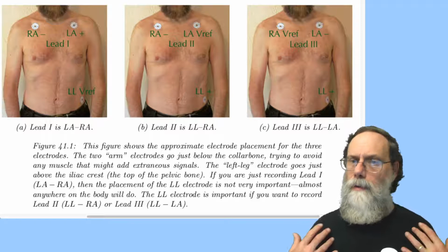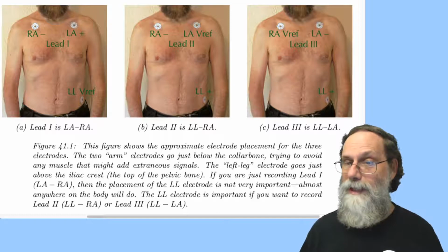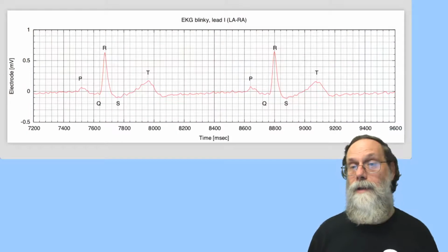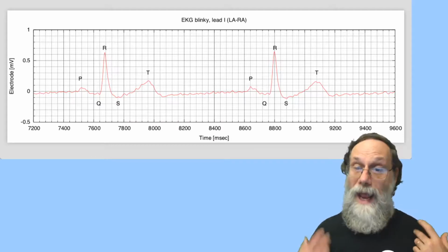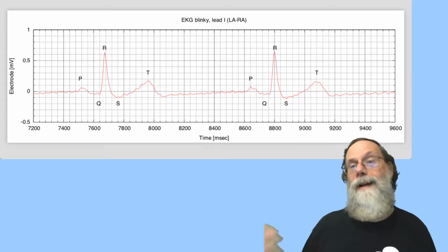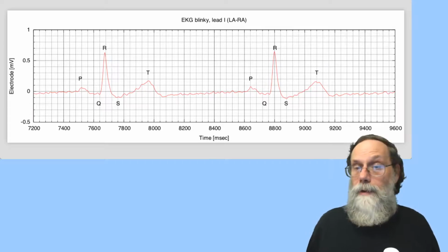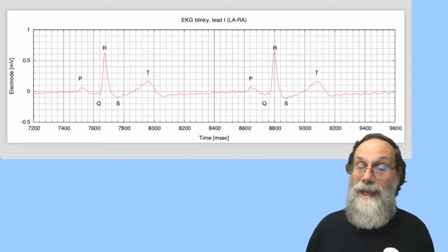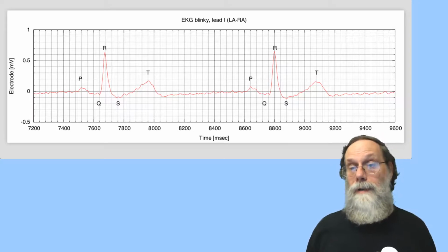Okay, so if you get the EKG signal working with your breadboard, save all that data, get your GNU plotting working so that you can get a nice plot like this. You want to make sure that your output is in millivolts, that is the millivolts at the electrodes. So you have to know what the gain is of your amplifier and compensate for that. So if your output is 1.2 volts, what does that mean? Nobody knows. But if you take that, what's the difference from your VREF? All right, now I've got it divided by the gain of the overall amplifier. That tells me how big the differential signal was coming in. That's the thing that you want to report in an EKG.